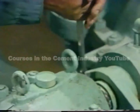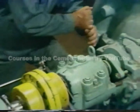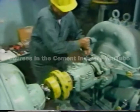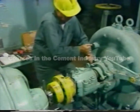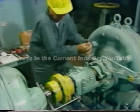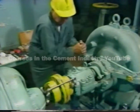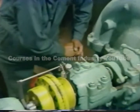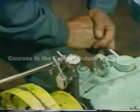The reason this is done is to make sure that the dials return to the 0 position when they're back at the starting point. That will be a good indication as to whether or not the mounting is rigid enough. If the dials don't return to 0 when they get back to the starting point, it means either that the shaft is moving along its axis due to thrust, or that the mounting isn't rigid enough. In our job, both dials return right to 0, so the technician knows that he has a good mounting for the dials.